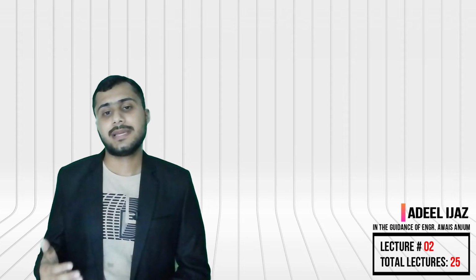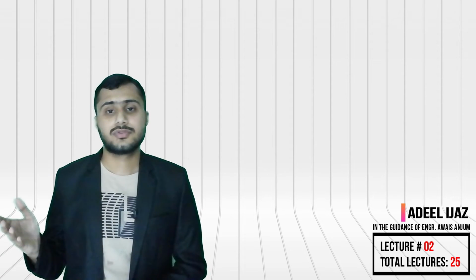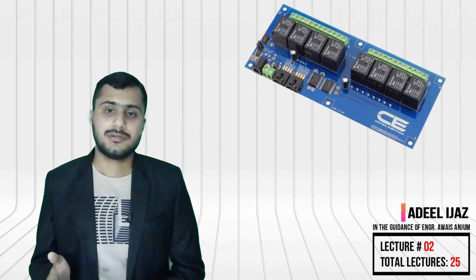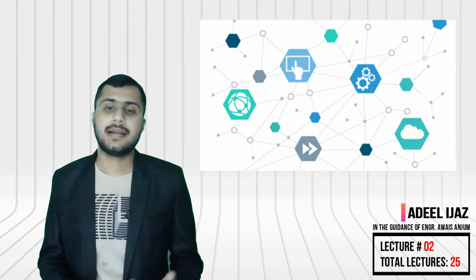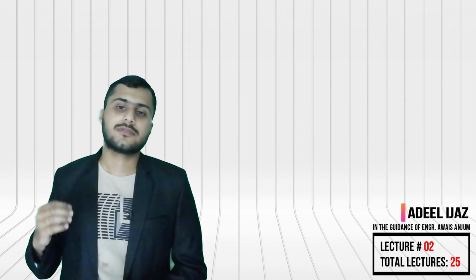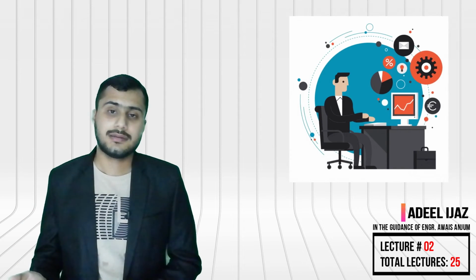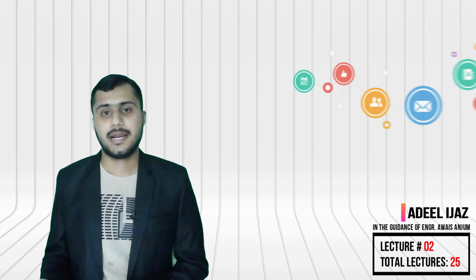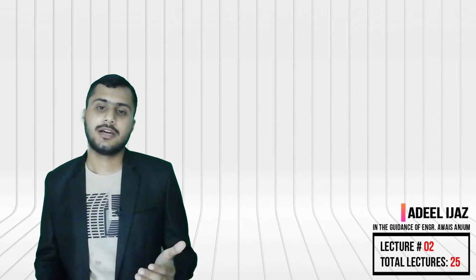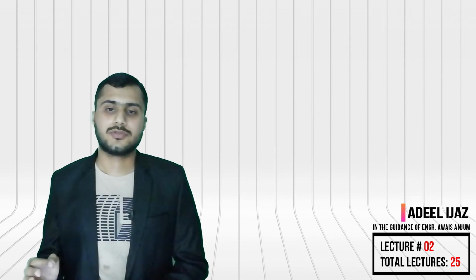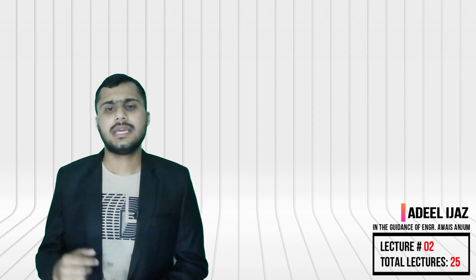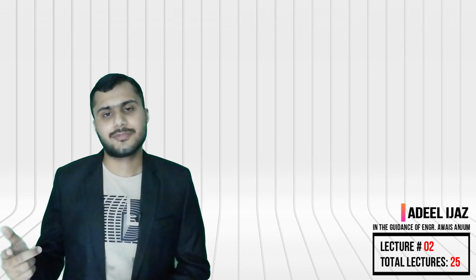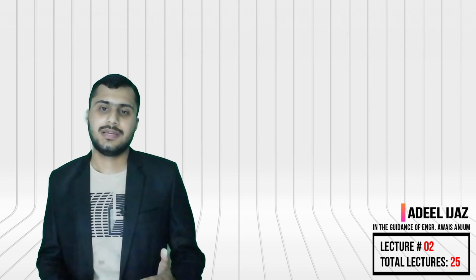The functionality of PLC has evolved over the years to include sequential relay control, motion control, process control, distributed control systems, and networking. The capabilities of some new PLC include data handling, storage, processing power, and communication approximately equivalent to some desktop computers. The most basic function of a programmable controller is to emulate the function of electromechanical relays. A unique address is given to each discrete input, and a PLC instruction can test if the input state is on or off.